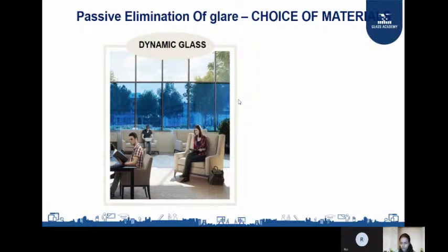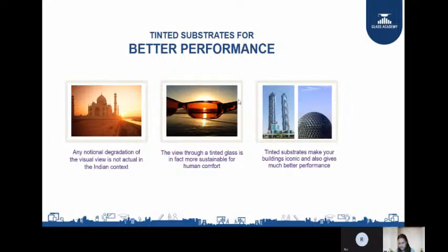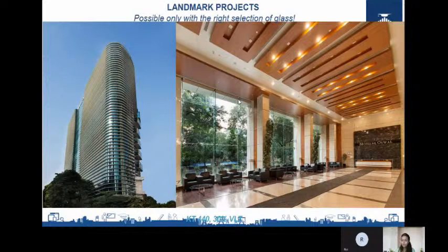So what are the products? When it comes to E-rated glass, there are two products, Keralite R and Pyroswiss. These are the performances mentioned here, the applications where you can use them, and the different thicknesses. When it comes to the EW category, we have Contraflame Door and Contraflame Light. And third, we have EI rated glass. There is a product called Contraflame Structure. This will be EI rated glass. Again, this is the EI rated glass.